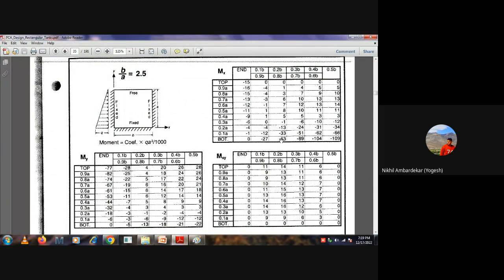So most of the time, you have to find the worst bending moment, the worst case. This is the maximum, above that there will not be anything. So we need to find the maximum bending moment for Mx and My. How can we calculate that?